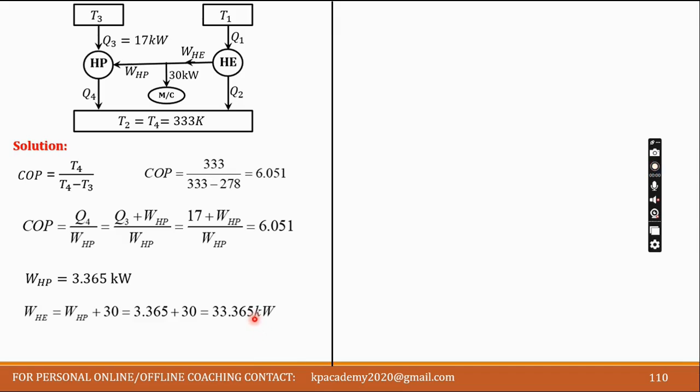We need to find out Q4 now. That was our target, right? So how do we find that? Q4 is equal to Q3 plus WHP, right? Q3 is 17 and WHP we just calculated as 3.365. So after putting the values, what do we get? The Q4 value, that is the heat rejected by the heat pump to the sink, is 20.365 kilowatt. So out of two values, Q2 and Q4, we got Q4.